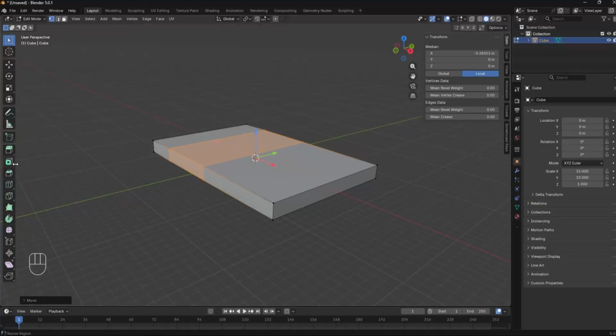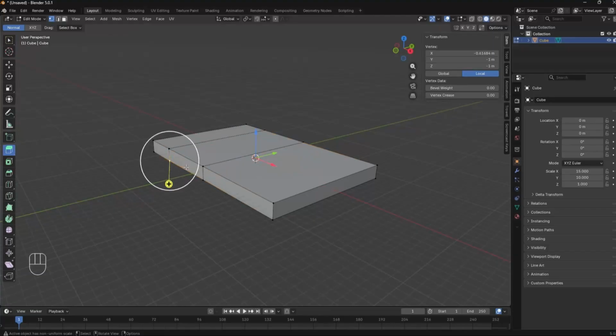And then what I want to do is we're going to select this. Oh, I want the face, so I can hit this up here. I can also hit a number 3. If I hit 1 it will be vertex, 2 is a line, and 3 is a face. In this case, we'll hit that, and we'll just extrude it outwards a bit.